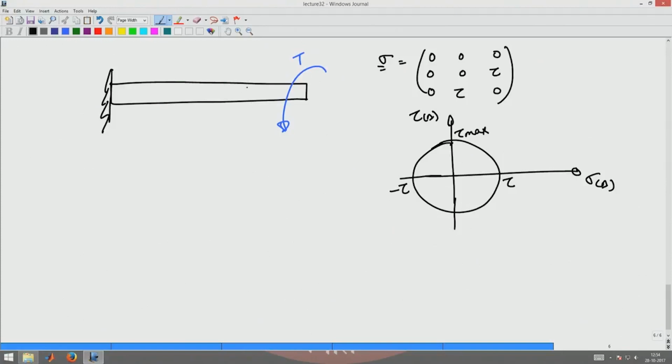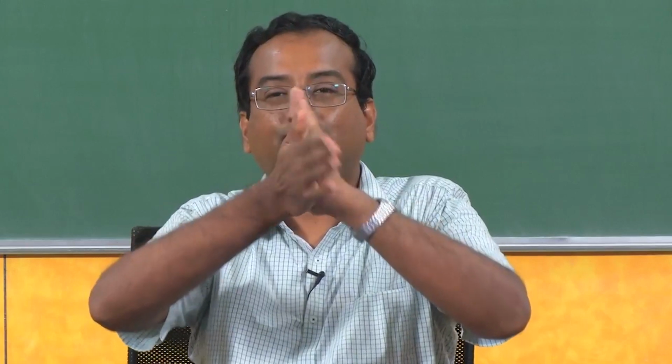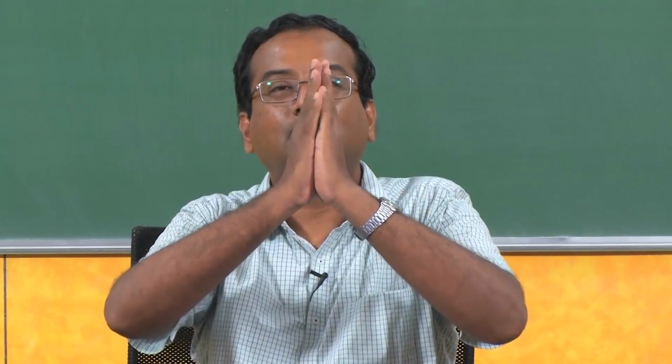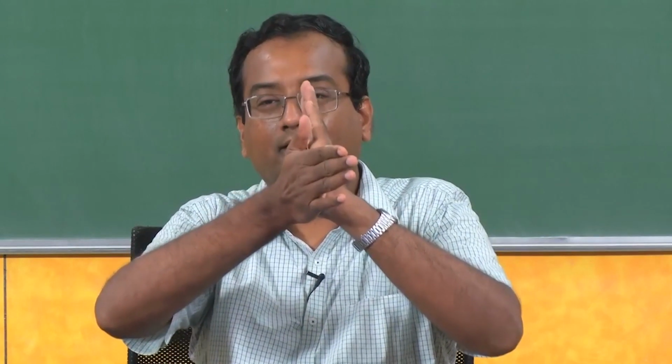So, what will happen is, when I twist it, the surfaces which are in torsion, which are in shear, will just shear off like this. In torsion the surface will shear off like that, that is, if the shear stress were to govern the failure theory.